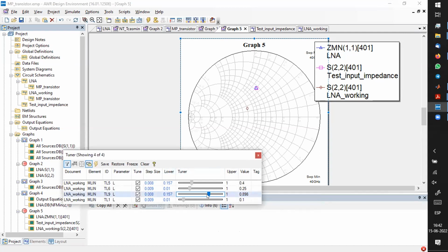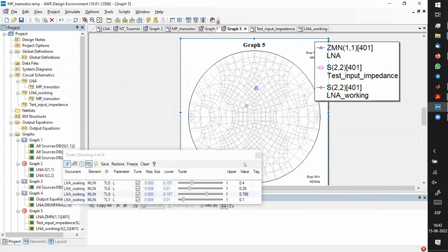So now this is your last option to move on the admittance plane. Then you have one series line, right? So you go higher, I mean higher on the Smith chart. Remember, you have one series line left, so you will go around it. So you need to go maybe a bit higher. Remember, a series line takes you around the Smith chart.